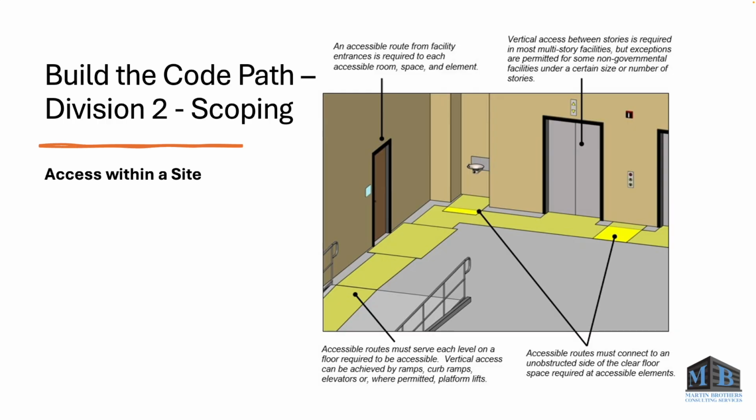The space in front of this drinking fountain is connected to our circulation path here, our accessible route. And it continues on going towards the right of the image, connecting to an elevator and the elevator's call buttons. So yeah, everything inside that is accessible and required to be accessible must be connected by an accessible route.